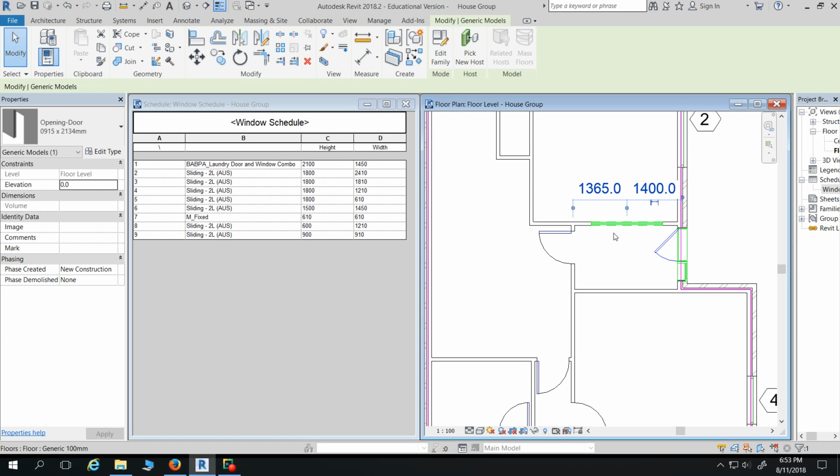I have a question. This part is not fixed, right? You can move it. There's a way to constrain it or something. That's a good question. Now that you've got your windows in the ideal location, you don't want them moving, do you? So you can constrain them via dimensions. Let's say we're doing design development at this stage, and you just want the window roughly centered to the room, or some of them are offset to the room.